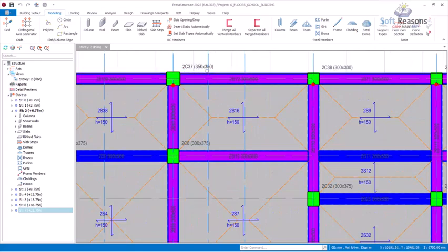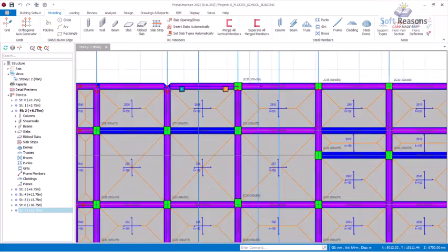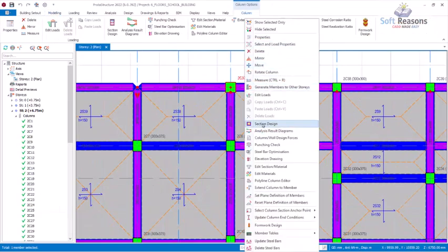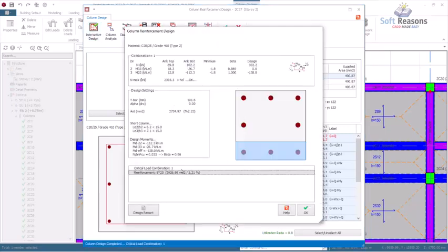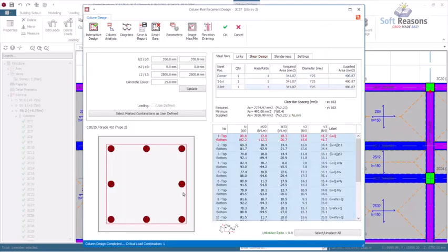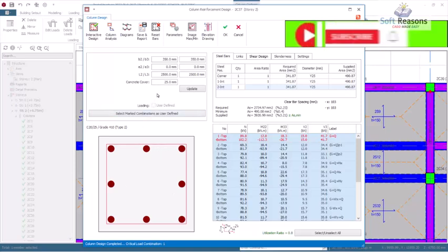All right, so these ones are 350 by 350. Okay, so we may also check what is the design of the reinforcement. So you can see at 350 by 350 we are actually having about how many reinforcement here? 8 numbers of reinforcement at U ratio 0.8. Okay, if I try to interact this now, you see it is 8Y25. So you can see the column sections here, the column sections here is 350 by 350, and the reinforcement, as you can see, is quite very high.